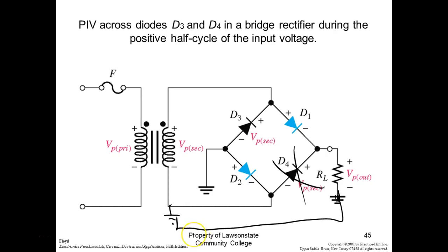Now what we could do is disconnect my ground off my meter, move it off the resistor and over to the transformer, and we can measure it and then bring it back. But that's one of the problems we have with a full wave: I cannot look across the transformer and the load at the same time. Yeah. Now we could come over here. I think it'll show us half of it. Let's go over and see what we can look at.